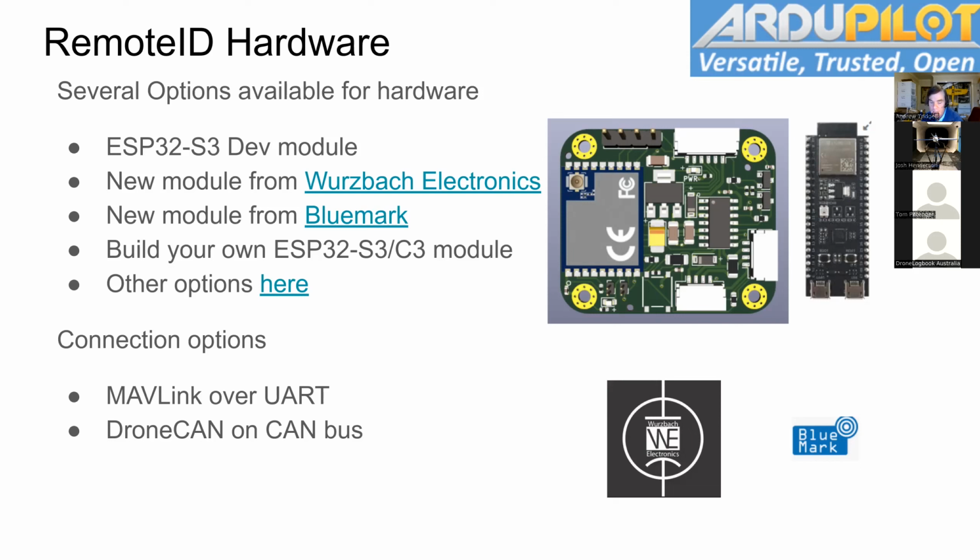Adding that on, you could actually build your own transmitter module by taking an ESP32 dev board, adding a CAN transceiver, putting it in a 3D printed box and putting a nice antenna on it. You can get versions of this dev board that take UFL antenna connectors. You're going to need a decent antenna setup. So you could roll your own that way.